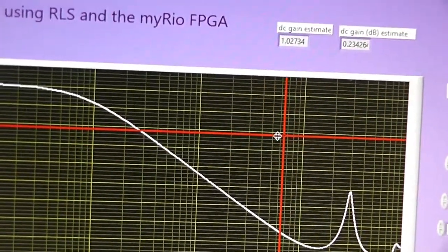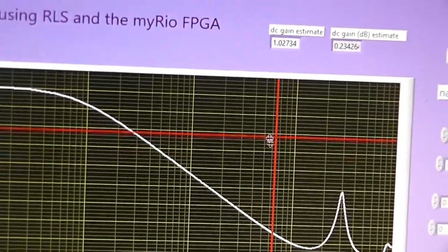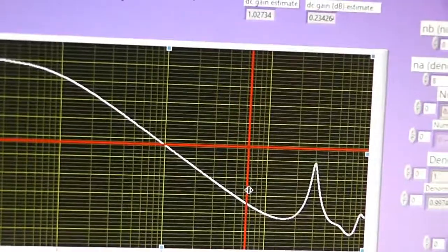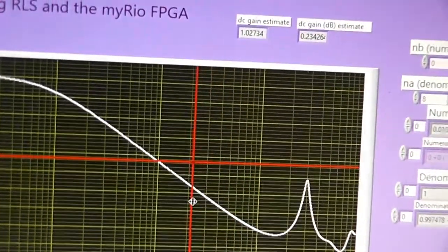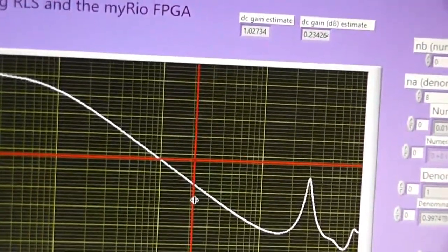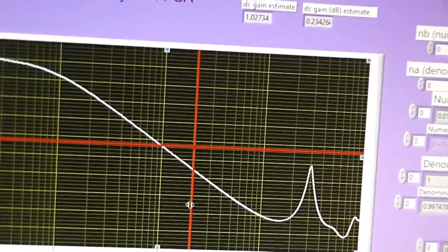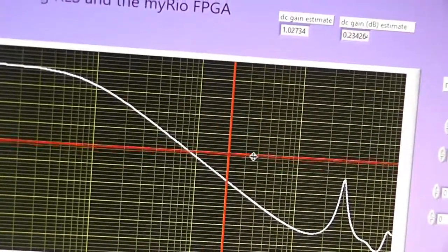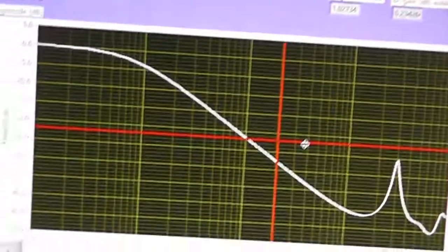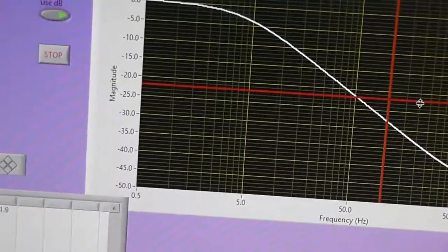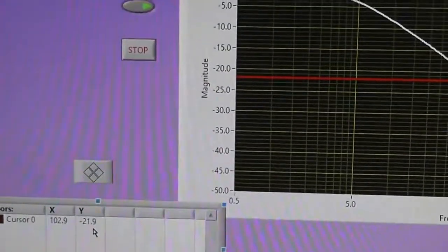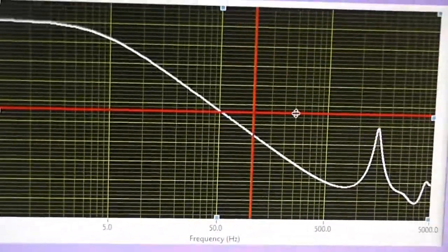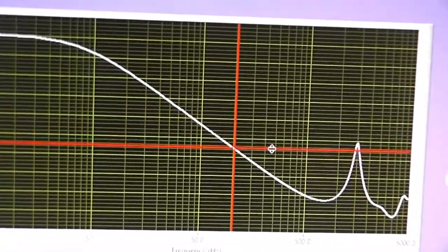So in an octave, which is a doubling in frequency, let's go there, 50 Hertz. So to 100 Hertz is here. That's 100 Hertz where this one is. So we're going from here to here, 100 Hertz. Should go down 6 dB. So it does it. At that point it is minus 21. I might say minus 22 dB, minus 21.9, and down here it should be twice.